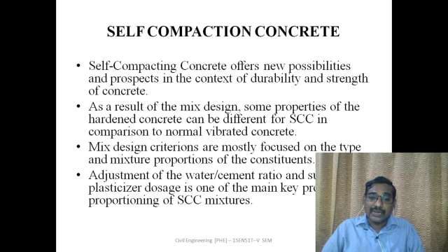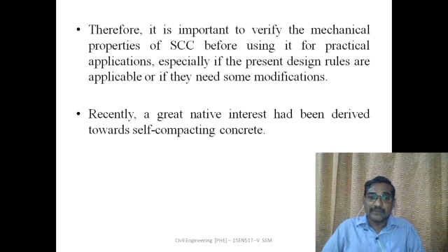Adjustment of water cement ratio and super plasticizers, admixtures are important in self compaction concrete mixture. It is important to verify the mechanical properties of self compacting concrete before using it for practical applications, especially if the present design rules are applicable or if they need some modifications.